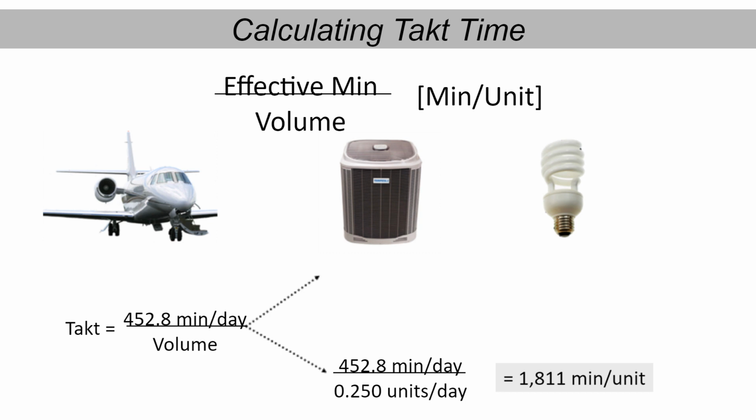Another risk of long takt times is quality. In assembly environments, you tend to cover past work with current work. Should there be a mistake in past work, you'll be hiding those mistakes, converting mistakes into defective products. In the case of long takt times, you have to consider forcing a rotation scheme that makes operators move in and out of workstations through time frames much shorter than takt.